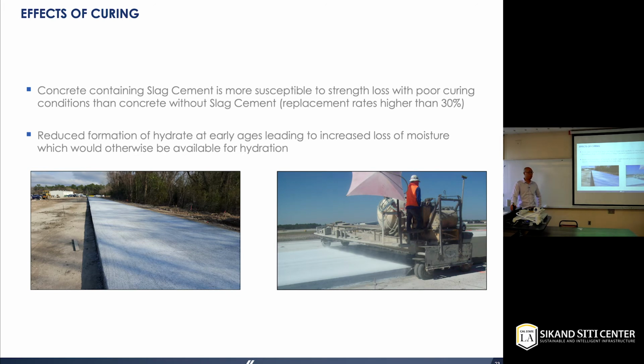Both reactions need water to ensure the chemical reactions take place, so you have to keep moisture in your concrete mix. What you have to do is put the right amount of curing compound on your concrete at the right time. We recommend that after you finish your concrete, you immediately put on the curing compound at the right rate to keep moisture in your concrete and ensure you gain the long-term strength.